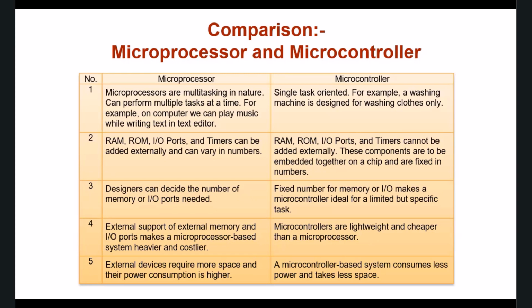Because when we are using the microprocessor, external memory and input-output devices have to be connected, the cost of the hardware increases. And that's why the microprocessor-based devices are costly. That is not happening in case of the microcontrollers.